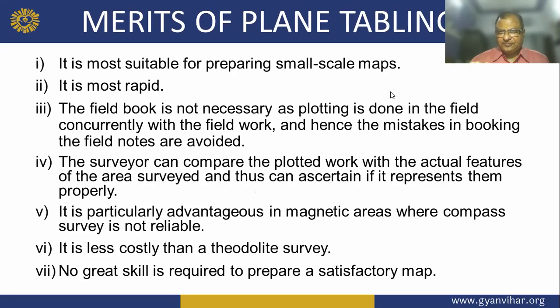Now, merits of the plane table. It is most suitable for preparing a small scale map and it is most rapid. The field book is not necessary as plotting is done in the field.